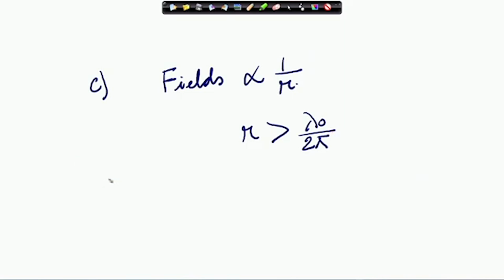But from criterion B, that the wave impedance is generally 377 ohm, that gives r as 3 lambda naught. And another criterion is that the far field structure can be approximated as a plane wave.